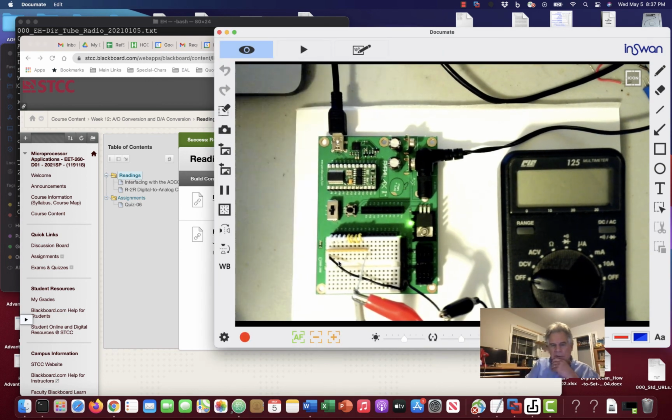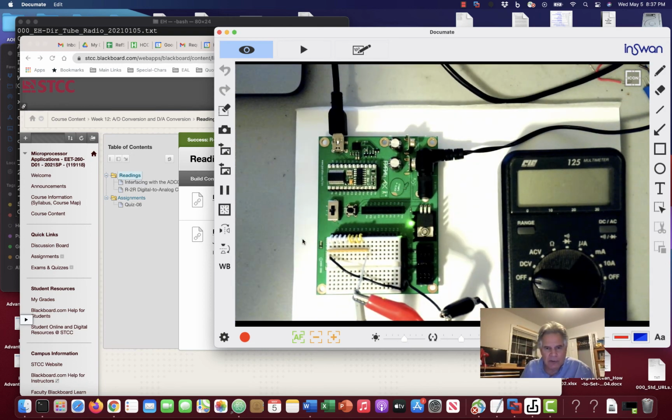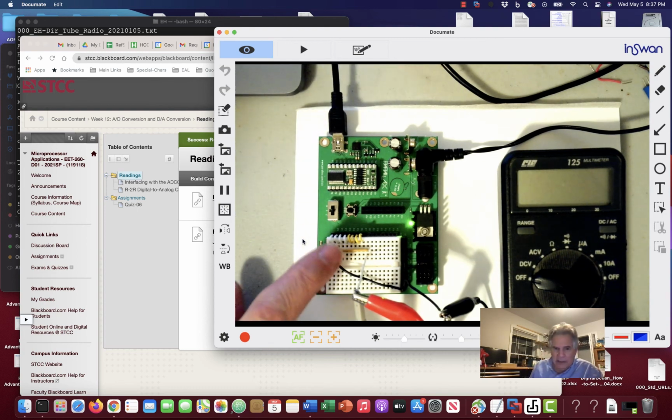We've talked about analog to digital converters. Now we're going to talk about digital to analog converters, and one particular converter we're going to explain. You can get integrated circuits, just like with analog to digital converters, that'll perform the digital to analog conversion. That is, you give it a number and out comes a voltage. That's also possible with a passive resistor network called an R2R ladder. And I have such a part right here.